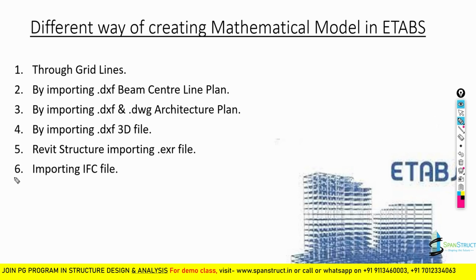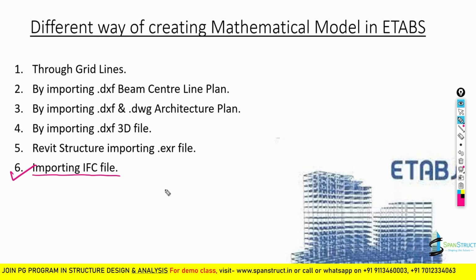Now come to the sixth method, which is importing an IFC file in Etabs. This method is common to other software also, like BIM software and other structural analysis software. Every structural analysis and BIM software has the capability to create an IFC file, and you can import and export that IFC file. IFC provides interoperability solutions between different software and applications.